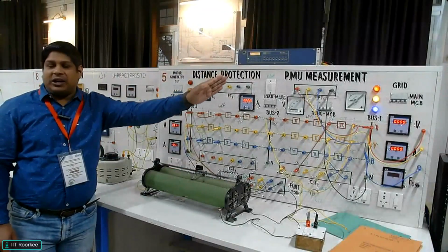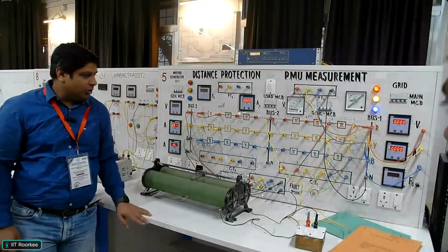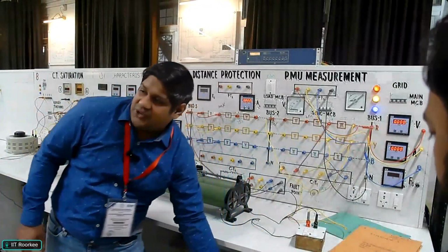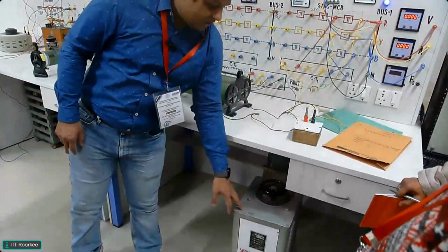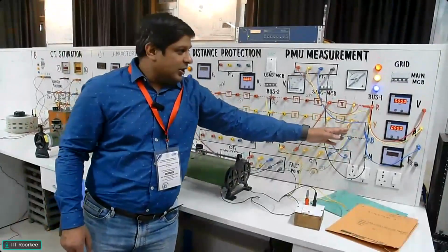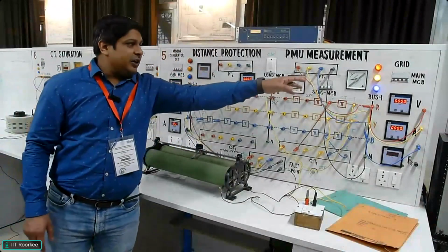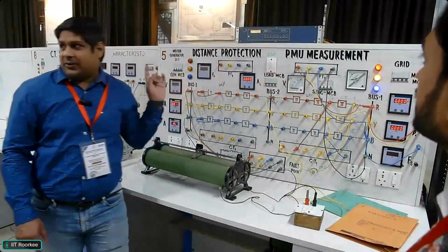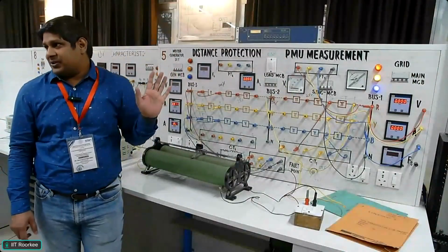The power is coming from the grid and flowing through this transmission line to the load. So now this is the transmission line. Through this 3-phase variac, we are giving 3-phase power, and we are giving it to the start of the bus. And then we have this transmission line. Actually, it is written here bus 1, bus 2, bus 3, but actually there is only one line, bus 1 to bus 3. And we have divided the line into multiple pi sections.